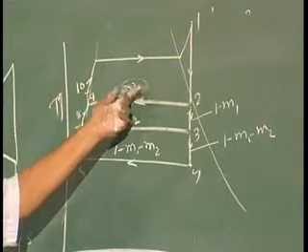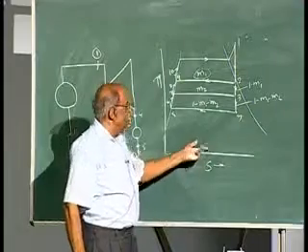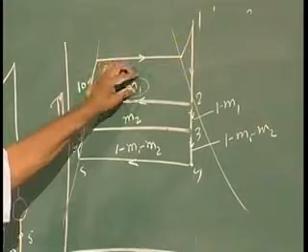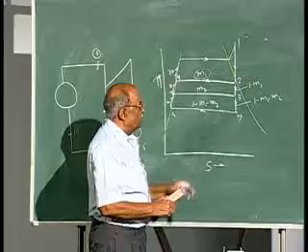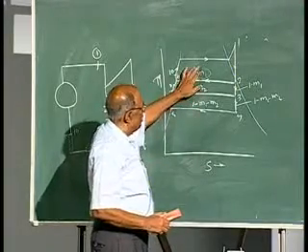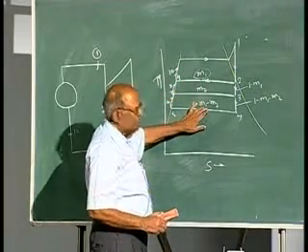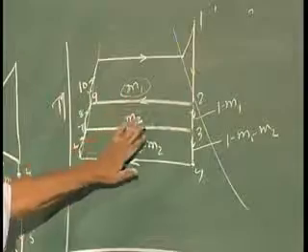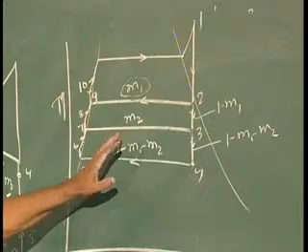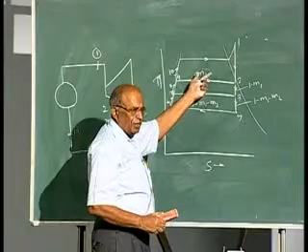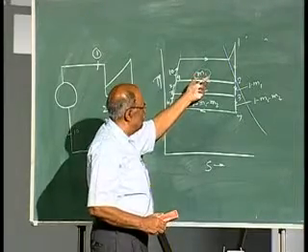and therefore the loss for this steam has been reduced to 0, that adds to the efficiency of the turbine, though the net work done in the cycle may be slightly less, because it is not expanding to the lowest pressure, but the loss is also being reduced, and reducing the losses is more important than the work that is being lost.